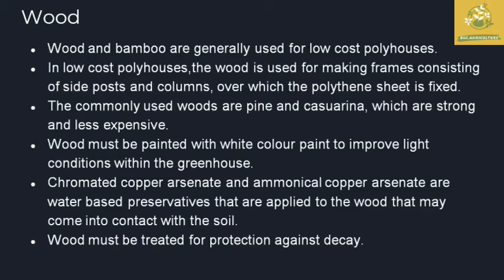But when we make a greenhouse or polyhouse based on wood, we must paint the wood white to improve the light conditions within the greenhouse. The wood must also be treated and protected from decaying, so that the low cost polyhouse has good longevity and life expectancy.